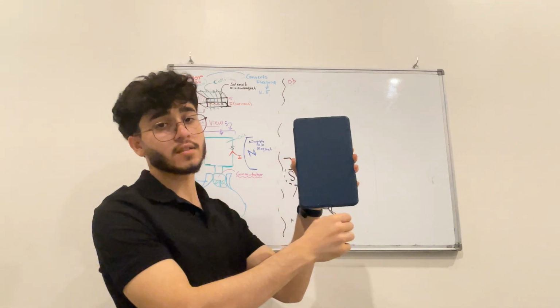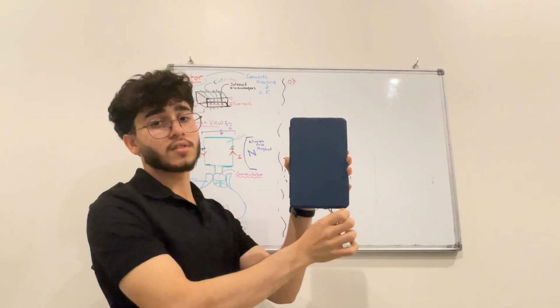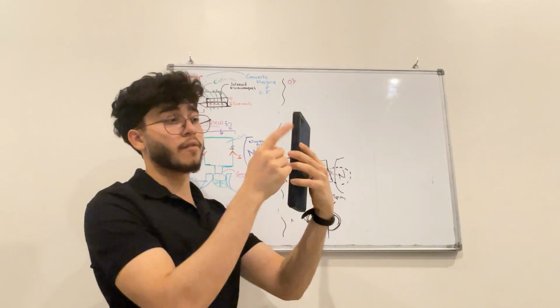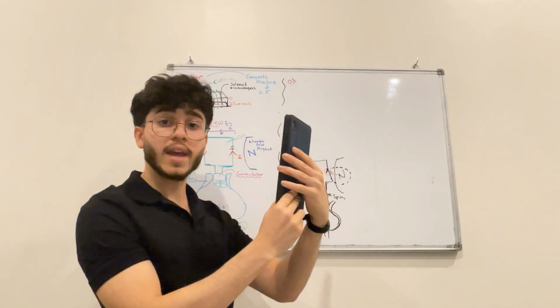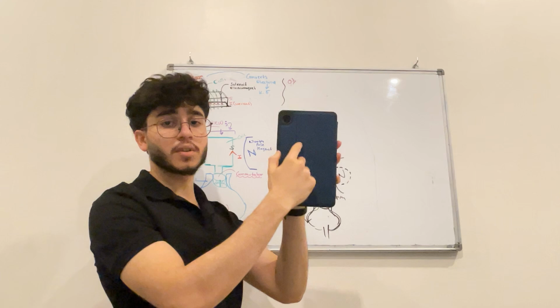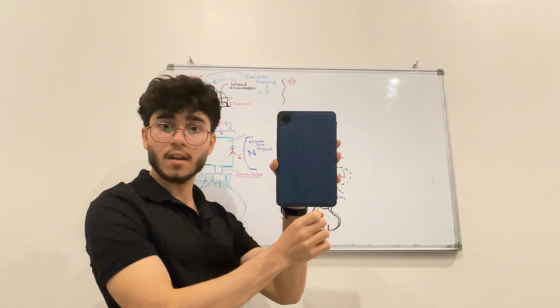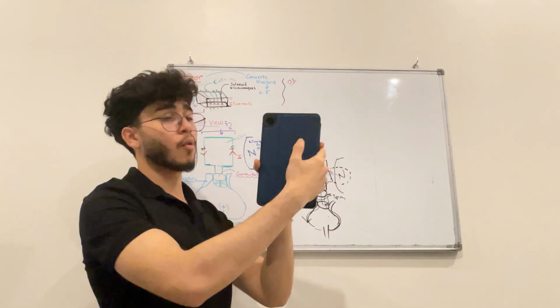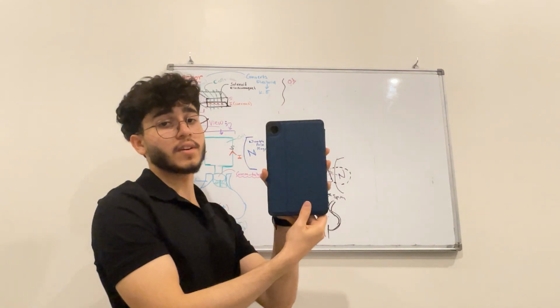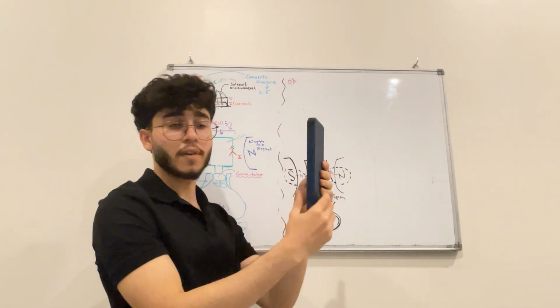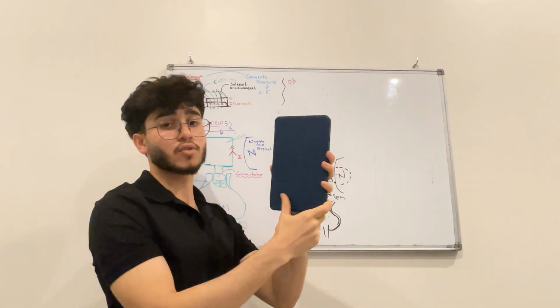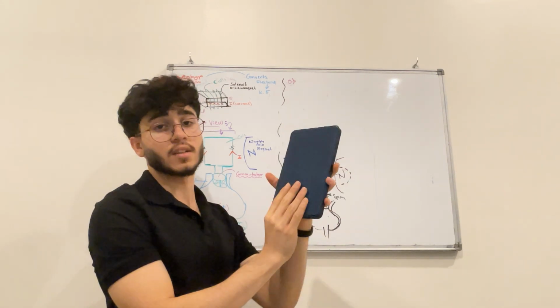By reversing the current, we have a commutator. Commutator is continuously spinning every time this one spins. So half spin, commutator spins, reverses the magnetic poles. Okay, it can spin now. As this one spins, the commutator just spins again. So reverse the poles over here. The magnets are the same, but this pole keeps reversing. So it will reverse the direction of the current. It will spin. Perfect. Reverse again. The commutator spins again. This will reverse the poles over here. It will spin, and we have a 360 degree.